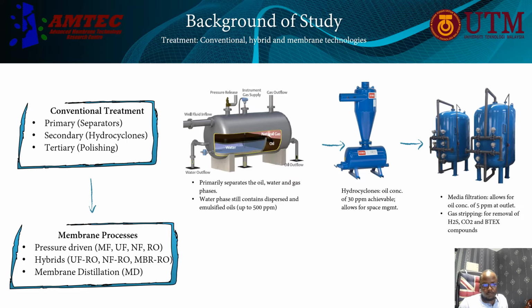So basically, for membrane processes, you have the pressure driven processes: microfiltration, ultrafiltration, nanofiltration, and reverse osmosis. Out of these, NF and RO mostly have been studied extensively for desalination of produced water or hypersaline water, as the case may be.